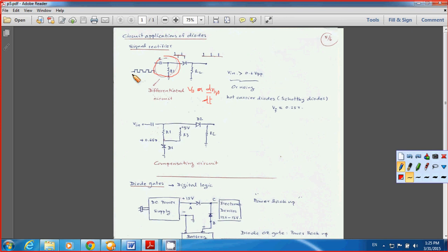So when you have a square wave as the input signal coming in, you end up with the output signal after the differentiator circuit like this one here, because it's just like you differentiate: at this point you go straight up, so you have a spike.